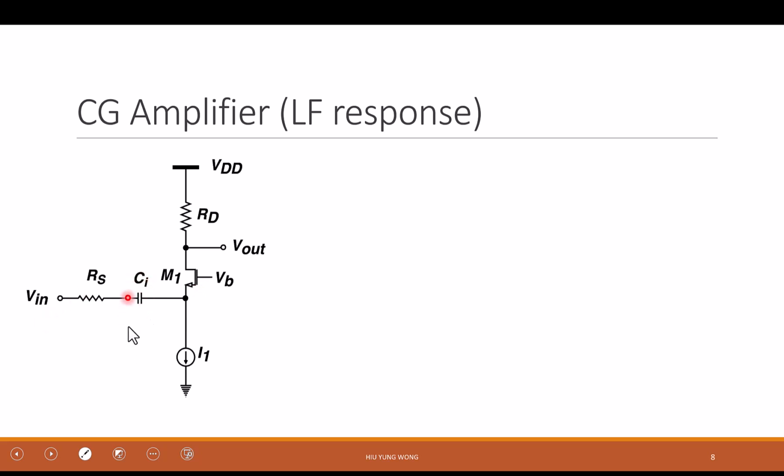So we have a capacitor, which is open for the DC voltage or current, but it is short, or low impedance, for the small signal, right? So that's why we have this circuit. For example, let's say this is biased at 1 milliampere, and then maybe this output is at 3 volts. And then I try to have some tiny input, maybe 10 millivolts. Then this will fluctuate, and eventually this one becomes maybe plus minus, for example, 0.1 volt as the gain.